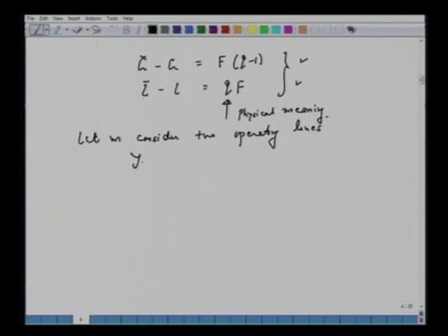So we have the equation of the operating line in two sections. Yg equals Lx plus DxD. Notice, the same as all we have done, we have written y equal L by G x plus D by G xD. So we have written in different form. So this is the operating line equation for enriching section, and L by G is same as R by R plus 1, etc. Or we have here xD by R plus 1.